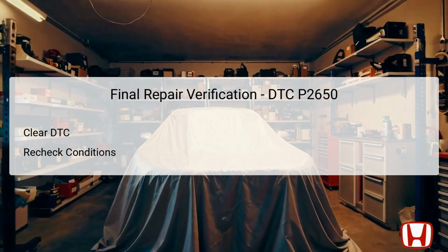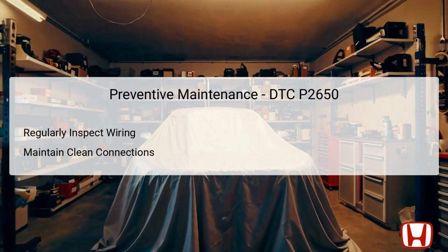If the DTC returns, further diagnostics may be necessary to explore other underlying problems, or ensure the components replaced were functioning perfectly after installation. Preventive maintenance is essential in avoiding DTC P2650 from recurring. Regularly inspecting the wiring harness for any signs of wear or damage can prevent unforeseen issues. Ensure all connectors are clean and free of corrosion to maintain optimal connectivity.